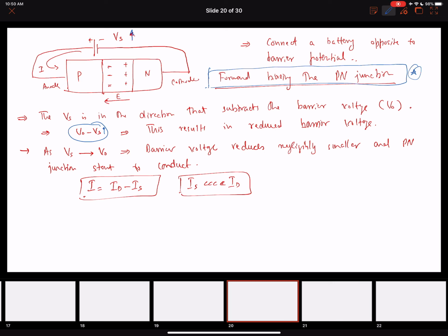This is also known as forward biasing the diode, right? So our diode was this. And initially we saw that this was a VI characteristic, right? We saw that when this is 0 volts, nothing is happening, and then the conduction starts to occur. Now, essentially, this is not true. There is a barrier potential, and the barrier potential is around, let's say, 0.7 volts. The conduction usually starts to occur at 0.7 volts, and then at 0.7 volts, we get a large rise in this current.